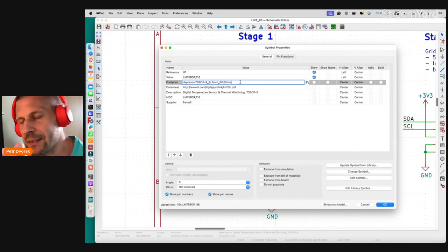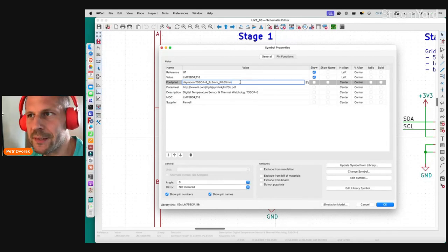In case I depended on the KiCAD libraries and something changed in the standard libraries, like they got rid of some footprints that I depended on, I would be lost. So I just copy the standard footprints into my own library, make some changes if I need.